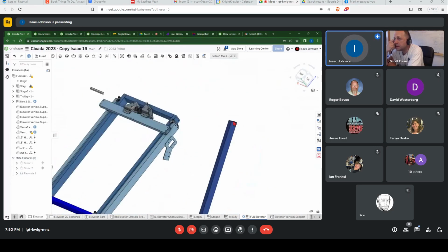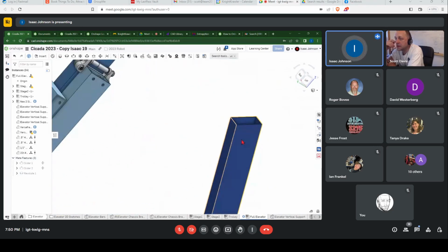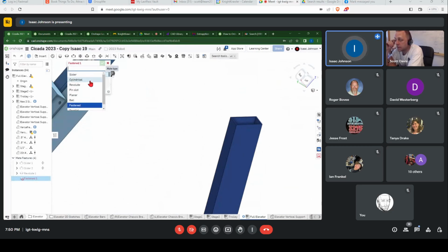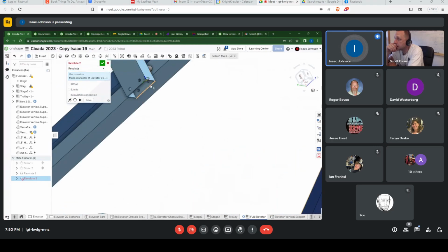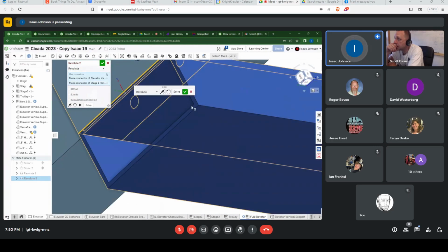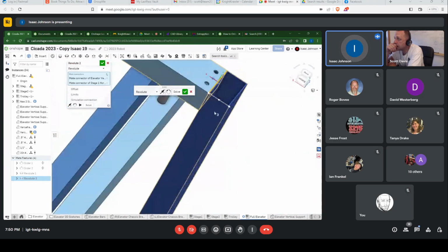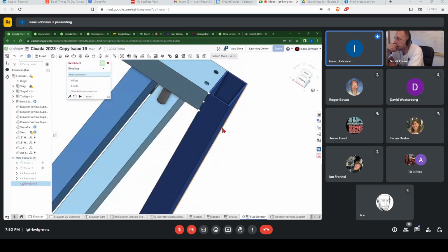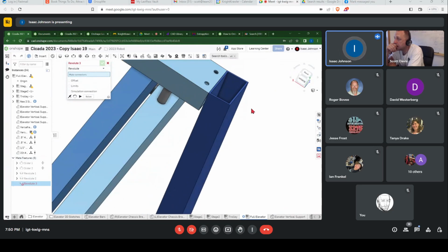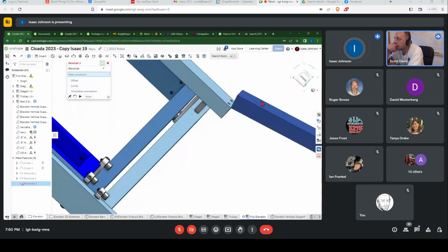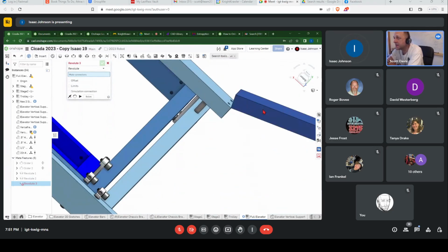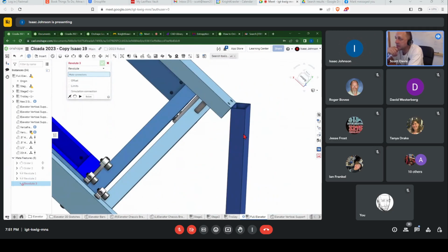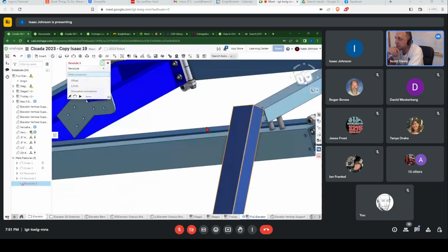If you do it without a circle, it won't spin in the circle. It'll instead spin along the edge that you did it. So if I take this edge and this edge, it's going to put them together like a fasten mate, except since I did the edges together, it's going to rotate around the edge, kind of like it's hinged. Got it. And that makes sense, right?